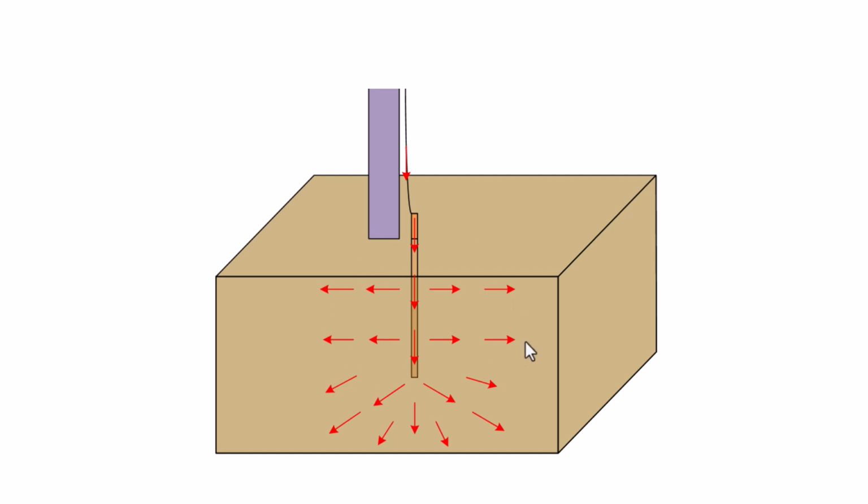Therefore, the current can penetrate through the ground. Here you can see in the sketch that the current comes here, goes through the grounding rod and distributes within the ground. This system shows a specific resistance, and this resistance is very important for some kind of functions in the power system. The grounding resistance is defined as the resistance from this connecting point to the remote ground, a ground that is located far from this electrode.